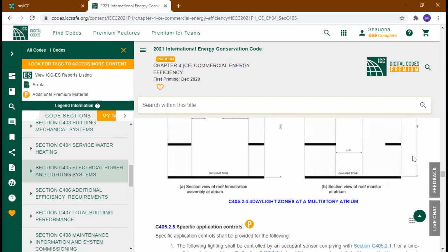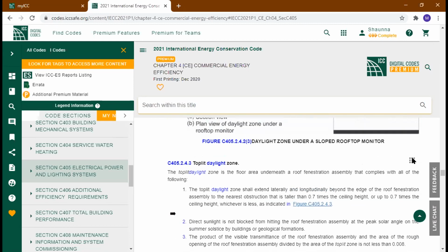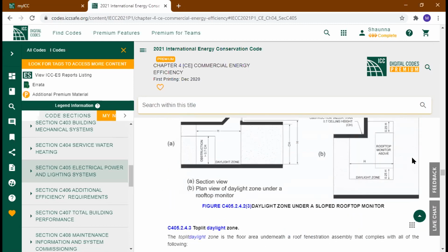It sounds like it's for the total wattage just within that daylighting zone. So each daylight zone is allowed up to 150. If you go more than 150 watts within that zone, you have to have a daylight responsive control to shut the lights off when there's enough light coming in the window. Right? So that's 150 watts.